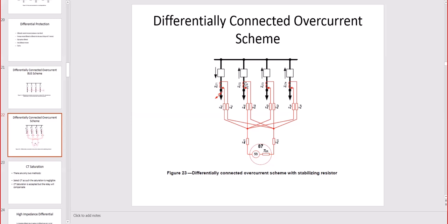That's why if we use feeder protection combined with this, we will block from tripping those other three feeders by using, for instance, a 67 relay. 67 is a directional overcurrent relay, and we will set up the relay to trip only for current going from the bus to the load. And any reverse power like this one, we may not want to trip. We may want to trip the breaker on the left and then leave the other three feeders alive. It is a better protection. But this example is how you implement the 87, and you can see the direction change from one to the other.